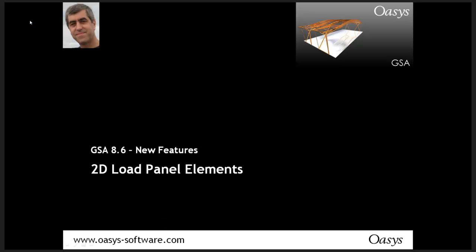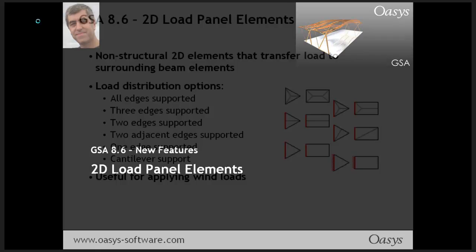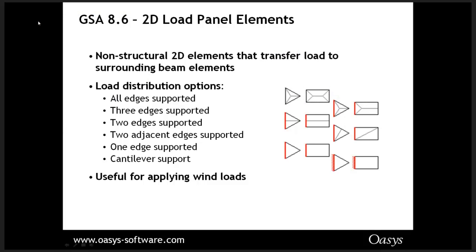Okay, moving on now to load panel elements. This is a new type of 2D element. The thing about this one is it's non-structural. So you put these elements in, but they don't actually take part in the analysis. They don't have any stiffness associated with them.